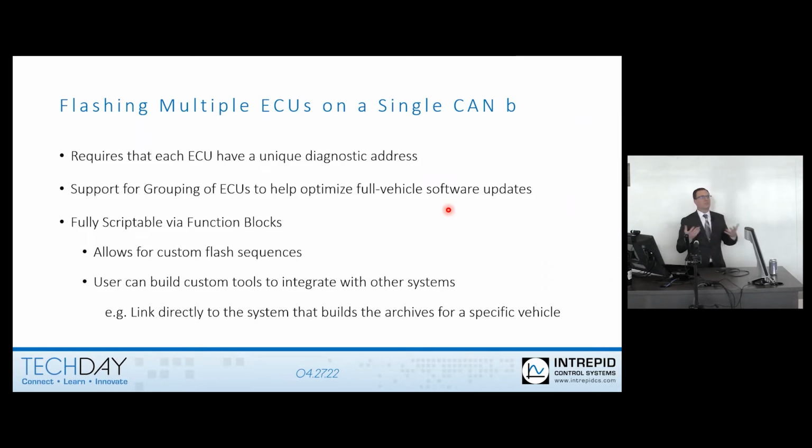So your common use case, right, is a vehicle. When you're flashing a vehicle, there's only one ECM in the vehicle, one TCM, that sort of thing. So you can flash all of those simultaneously in the vehicle, or a good large number of them. One of the things we also support is grouping. So if you want to set up 30 flashes, you can actually group them 15 at a time. One of the real common uses of this grouping is if you have to flash that gateway module. The first thing you probably want to do is flash the gateway module, because you can't flash the gateway while you're trying to have it maintain the traffic through to the ECUs behind it. So a lot of times you put that gateway module into group 1, and then put a batch of 15 into group 2, and maybe another batch of 15 modules into group 3. So that allows us to really help optimize things into a seamless operation.